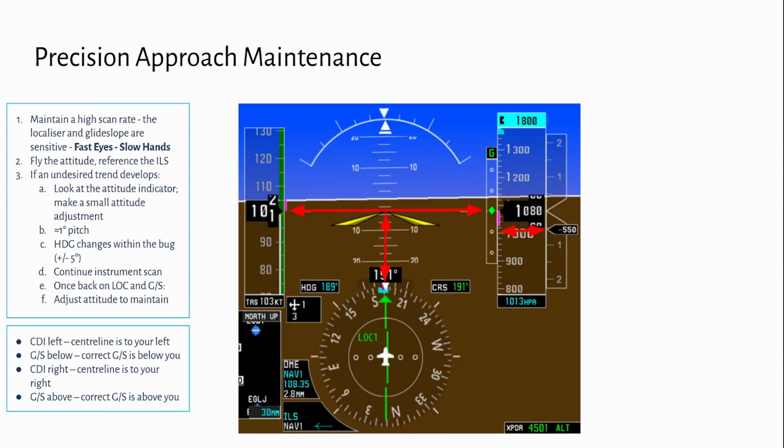So now we're going to go on to the chart. So this is the NDB ILS DME approach for runway 19 at Oxford. Not all charts will have a NDB. It depends on the airport and what's coupled in. It might be a VOR ILS DME approach. But generally, the charts all look relatively similar.